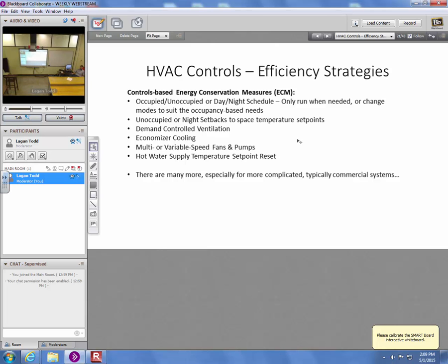So what you do instead is you have two separate set points: a night heating and a night cooling set point. So if your night cooling set point is 80, you won't cool till the space hits 80. And if the night heating set point is 60, you won't heat till it hits 60. So nothing will happen in between 60 and 80, but if you get up to 80, you'll cool. If you get down to 60, you'll start to heat. And you'll have a dead band around each of those night heating and cooling set points.